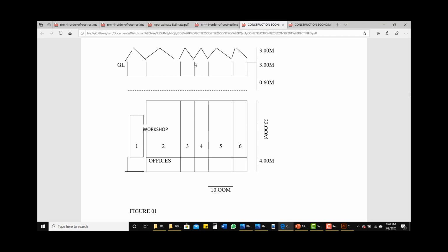Then also, coming back to the pitch roof that we use as an illustration, if your pitch roof is occupied, you measure from the top of your concrete foundation to 3/4 of the height of the roof. In this case, because our roof is not occupied, we measured halfway of the roof. But if it is occupied, you measure up to 3/4 of the roof from the top of your concrete foundation. So I believe that's helpful and that's clear enough.